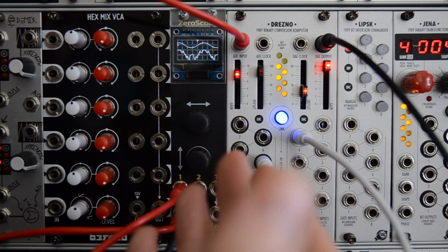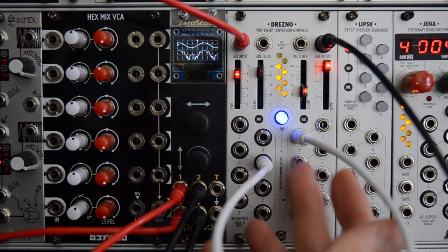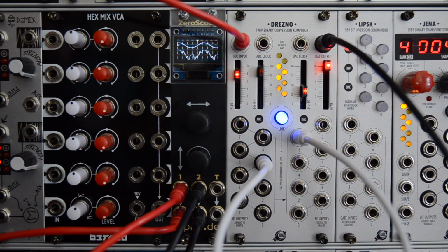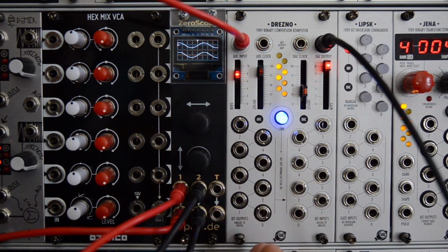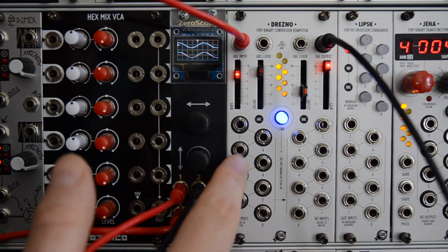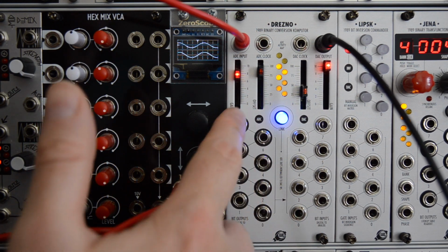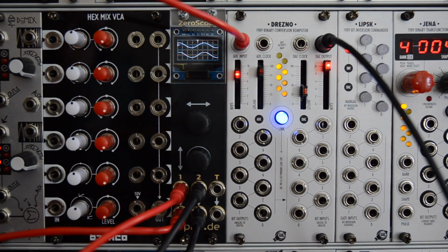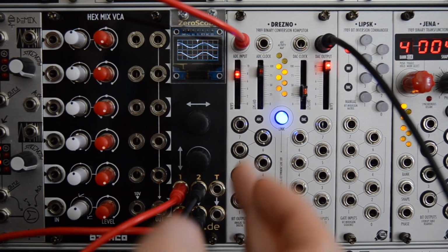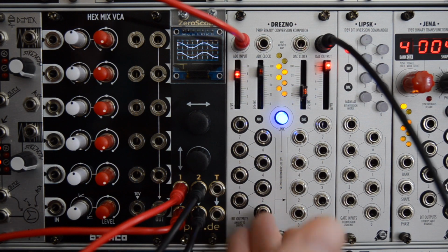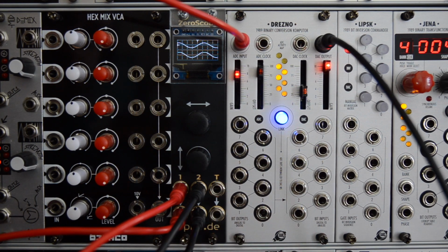And rest assured, I have no idea what's going to happen when I connect bit 4 to bit 6 or when I patch in a dummy cable. An easy way to look at this, and I will show you in a moment, is that the most significant bits, meaning the bits on the top, are changing the slowest, but cause the biggest change in the sound or in any voltage you send in. And the lower bits here, the least significant bits, are changing the quickest, but inflict the smallest amount of change in the sound or voltage.